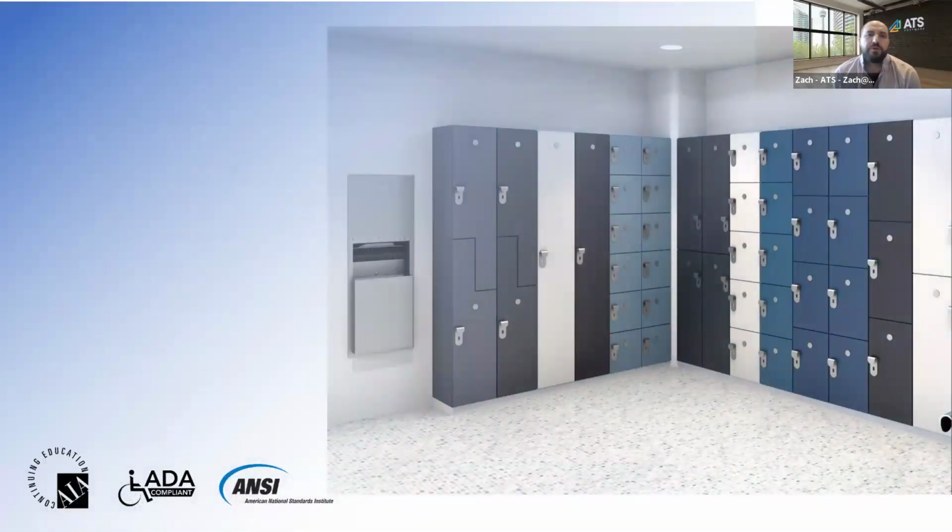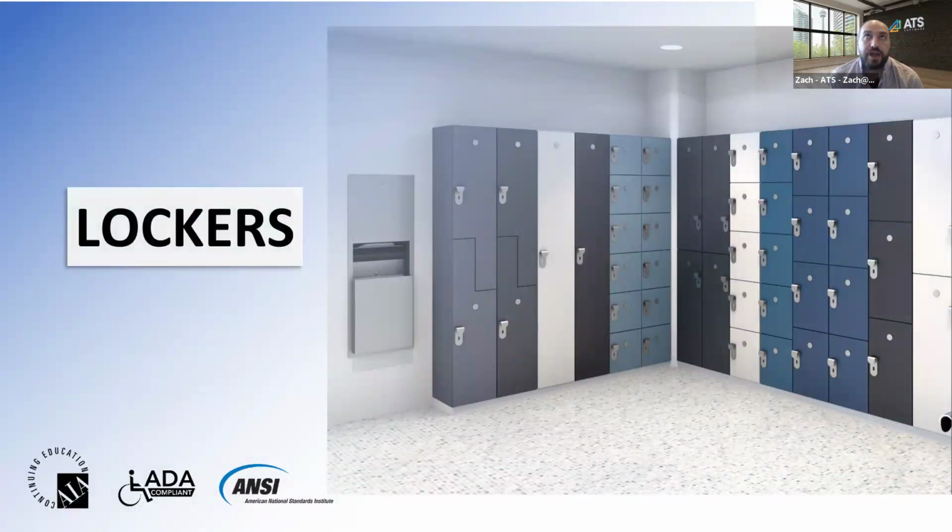And then in Canada here, we have similar height requirements on a manual flush valve. There's some specifics that go into how tall it can be above finished floor. And then we have additional specifics on the grab bar requirements, which are not as dictated in the ADA. So in Canada, it's required to have installed on each side a vertically mounted grab bar, not less than 600 millimeters long. And then there's also additional height requirements on the urinal itself, where the perch of the urinal has a specific height requirement above finished floor as well.